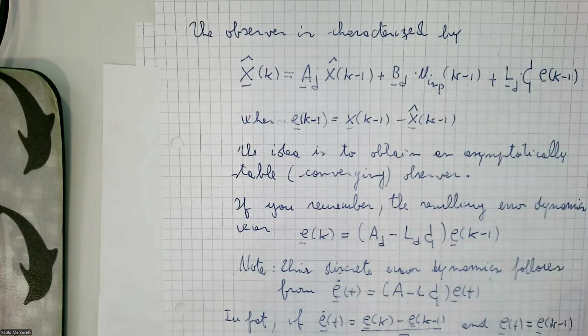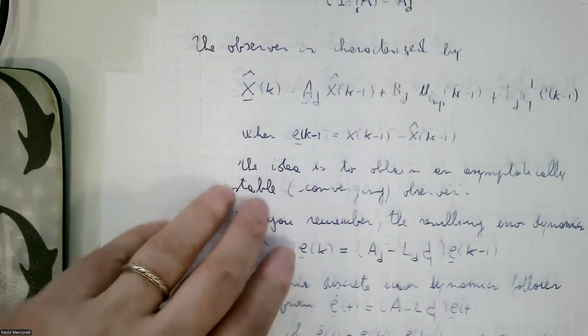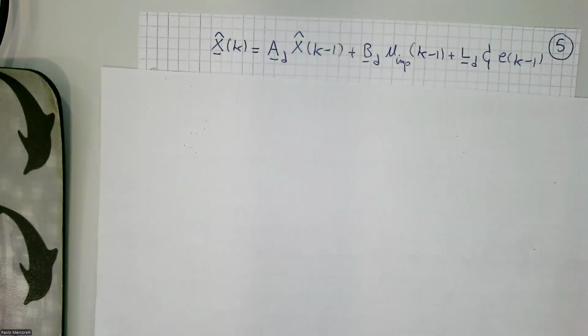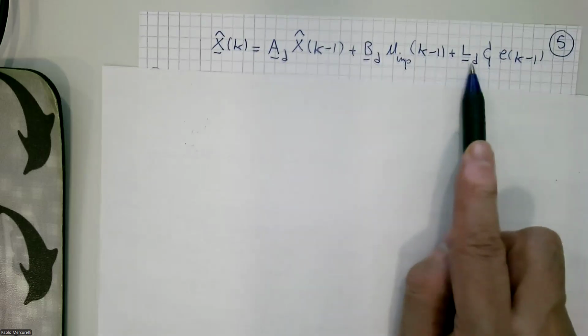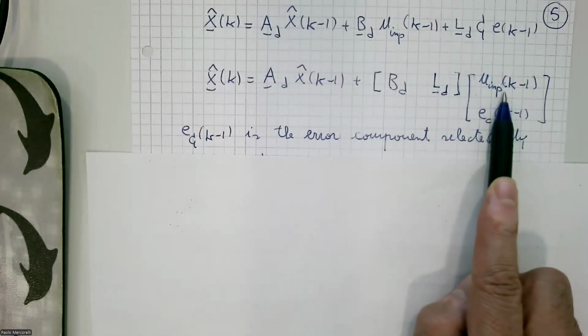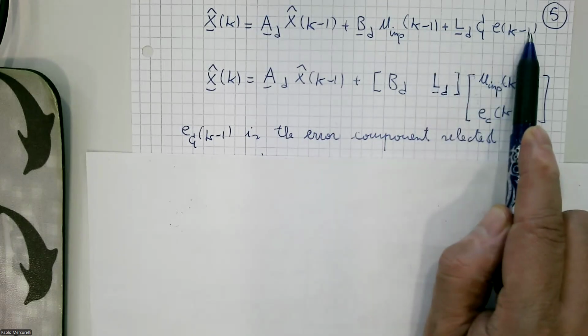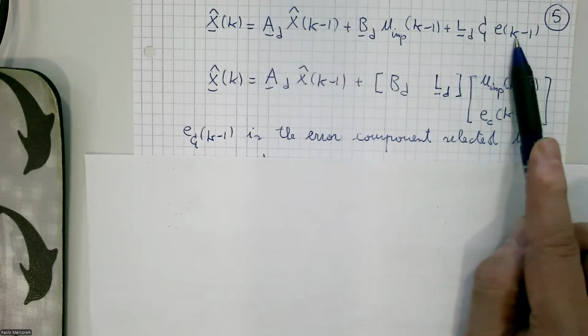Here we have the feedback. And somehow the observer is in control of the system, because here we have the feedback between what I am measuring and what I am observing. This means the system and the observer are strictly connected by the feedback. And this feedback allows us to control the error to zero, thanks to the matrix LD. I will show you. From here to here is clear, because what is the idea? We have two inputs, this and this. Did you agree?